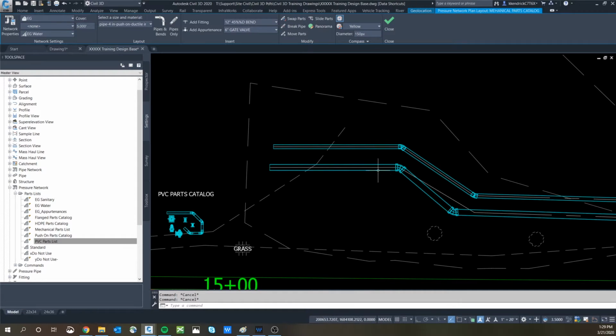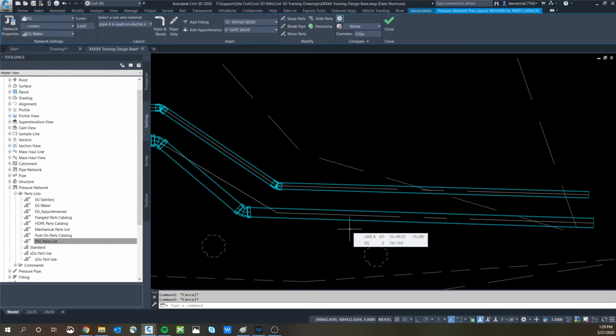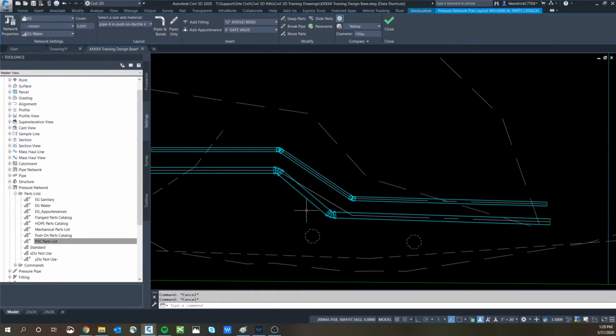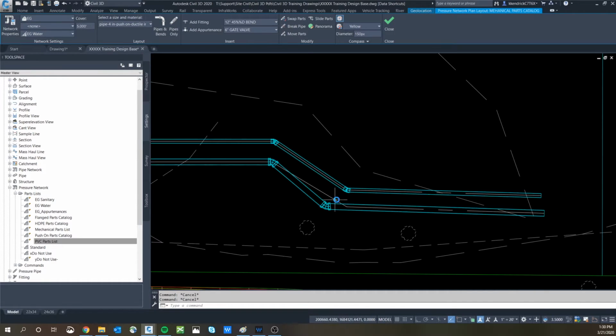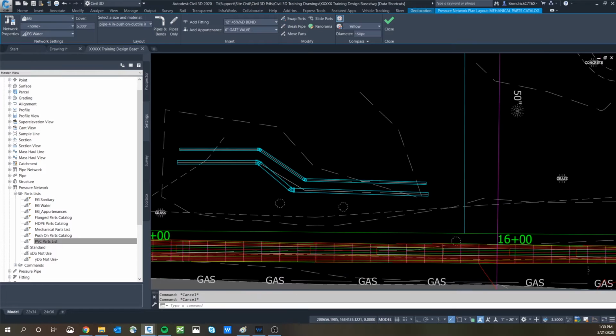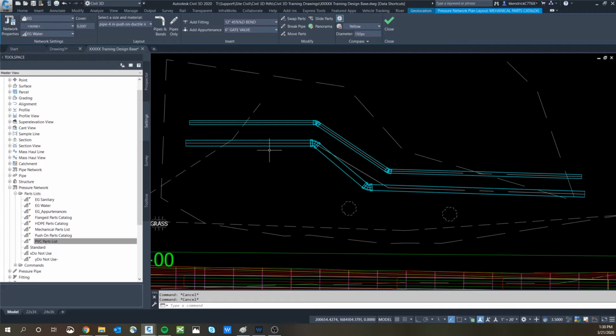Connect those up, and again, it's smarter to make sure these are correct 45-degree angles before you make the network. But if you do it and have to come back and fix it, you can disconnect parts and reconnect them after they are at the right bearing for the angle. I guess we can show how things work. I'll break apart and then we'll make a profile real quick, put this into profile view, and show how to add a vertical bend in profile view.